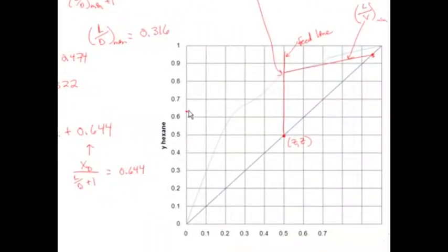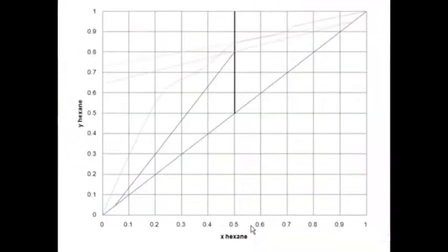The y-intercept is 0.644. And plot this. And then we will plot the bottom operating line. It goes through xb, xb. And the intersection of the top operating line and the feed looks like that. And let's go to the next page where we have this already plotted. This is our top operating line, and this is our bottom operating line.